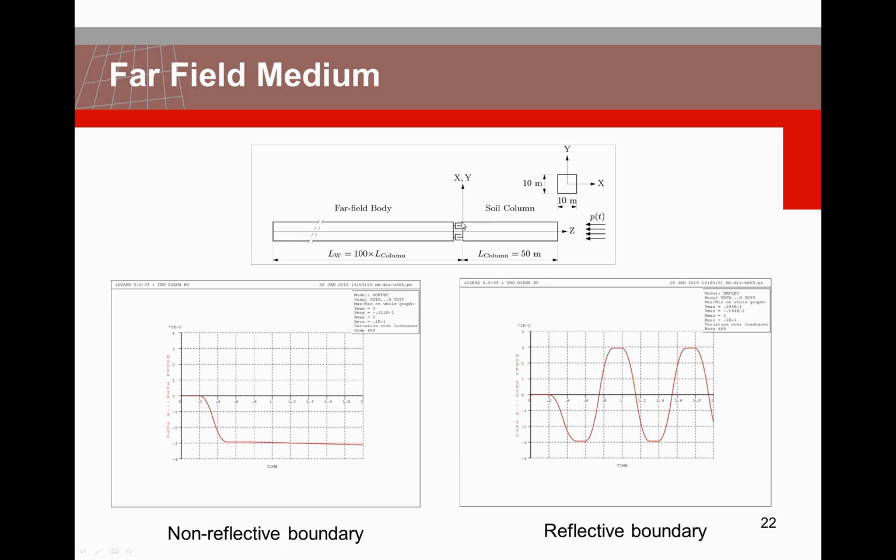What would have happened if we had placed here conventional supports? In that way, we also go down to -3, but at that time, the wave is traveling back, resulting that this part keeps vibrating, especially in this example where there is no damping at all. Then you have an impact, and what will happen is that the soil will keep going up and down, while in real life the wave should have gone into the far field and gone away.